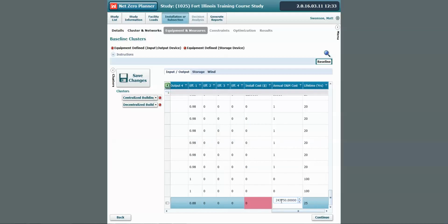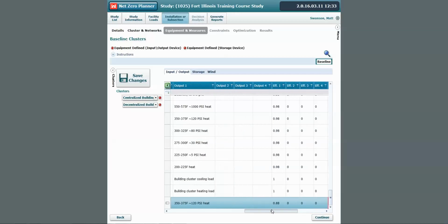So there are 4, it's going to be multiplied up for the total set of boilers. But here, again, this is partly related to running that central plant that's going to need some operations. There's going to be turnover and that sort of thing as well, controls and everything else. So those costs are associated with those boilers, and then a lifetime as well. If you have actual data, you can enter it here, and because it's a specific piece of equipment, we can use as a default number this annual O&M cost associated with a new boiler of that size.